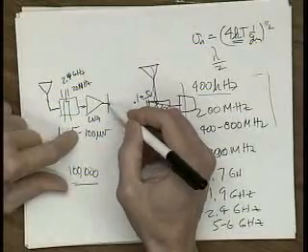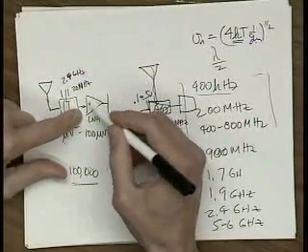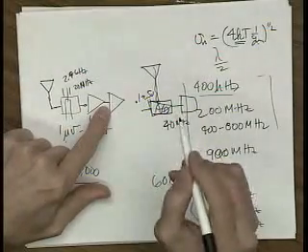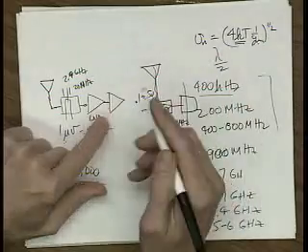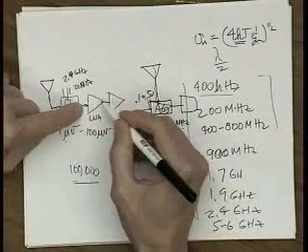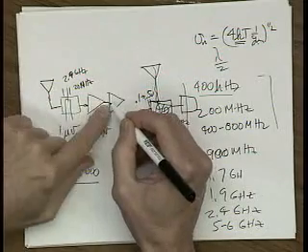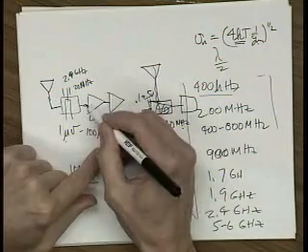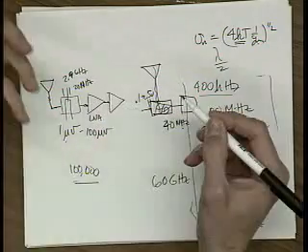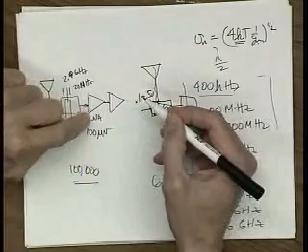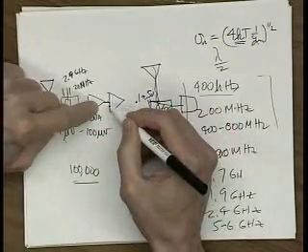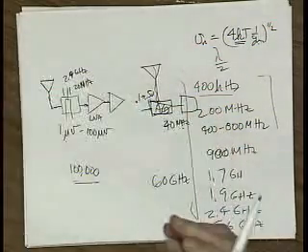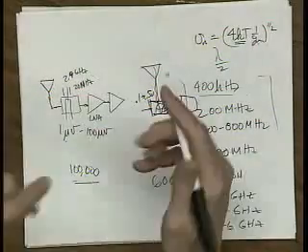But you can't do it in one stage, obviously. The first stage is the most critical one. This is really important for any kind of design generally. As you add noise here, you amplify the noise plus the signal. Then when you add noise here, the signal's bigger. So if the noise you add at this point is about the same as the noise you add here, the signal's bigger here, so the noise is less important. It's really the first stage that matters for noise. If you get enough gain in that first stage, then subsequent stages aren't a problem, because the signal's been amplified and the little noise you added is the same amount, so it doesn't have much effect.